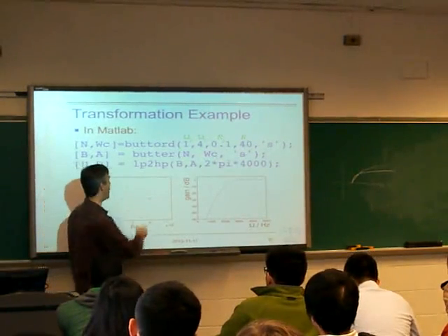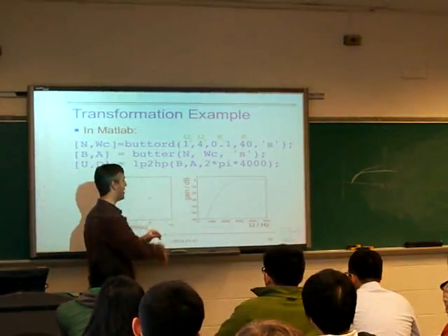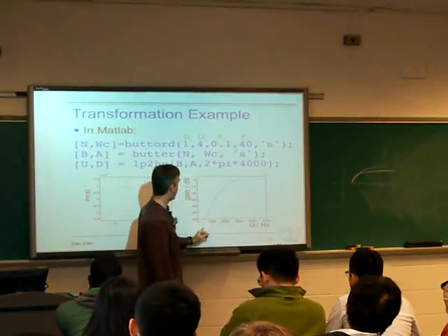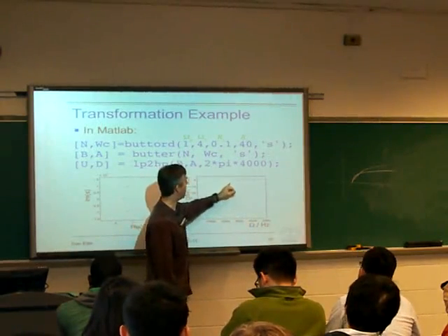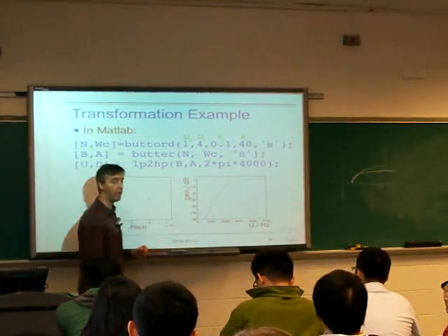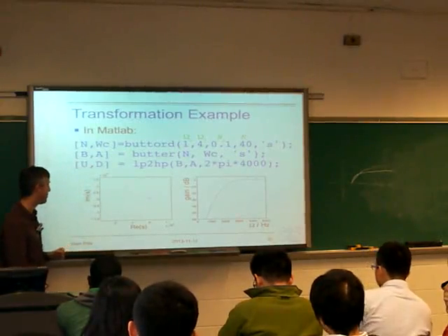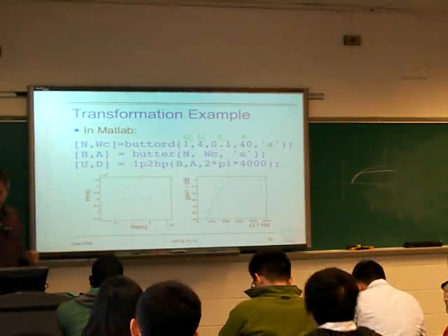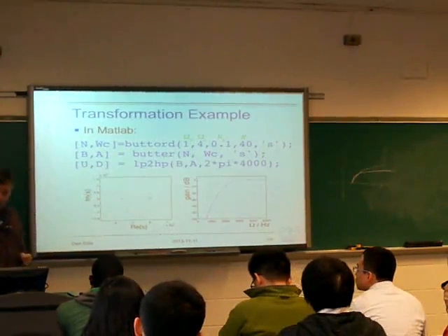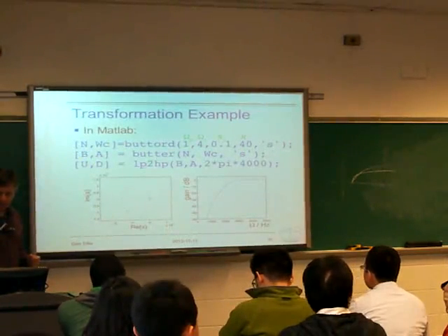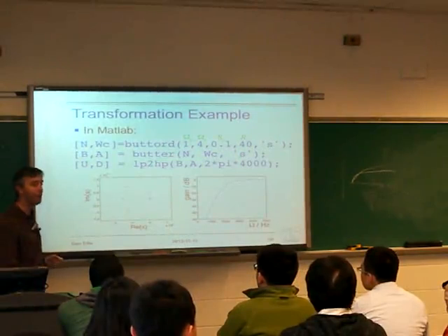And those n zeros just happen to exactly balance things so that what was flat and then rolled off now becomes something that has a high pass response and then is flat once you get above the cutoff frequency. I encourage you to try this out in MATLAB if you want to see how it works.